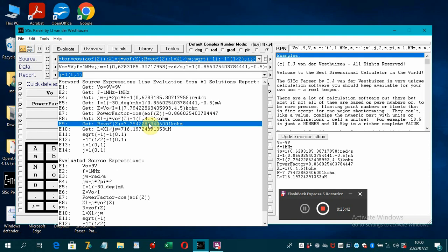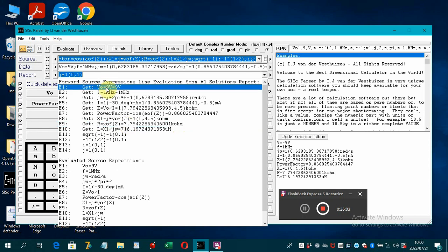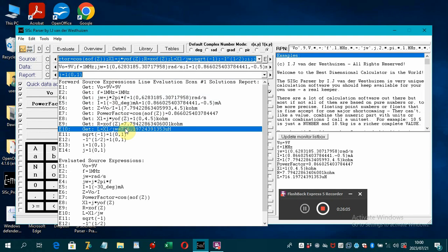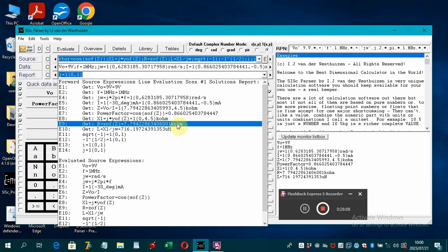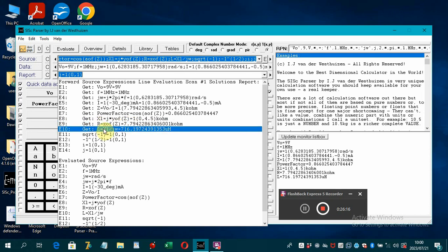You see, R is a real value. That's on a real plane because it's on an X-axis, and that is on a Y-axis. So this is your real thing that will give off heat. So you can calculate the power, it's easy. It's a simple real calculation. I haven't done it yet, but obviously the power can be calculated from the voltage and the current and the resistance. Or you can get the wattage or milliwatt, microwatt, whatever watts is involved here, but you can get the heating effect on the resistance. But L doesn't give off heat if it's a pure inductor.